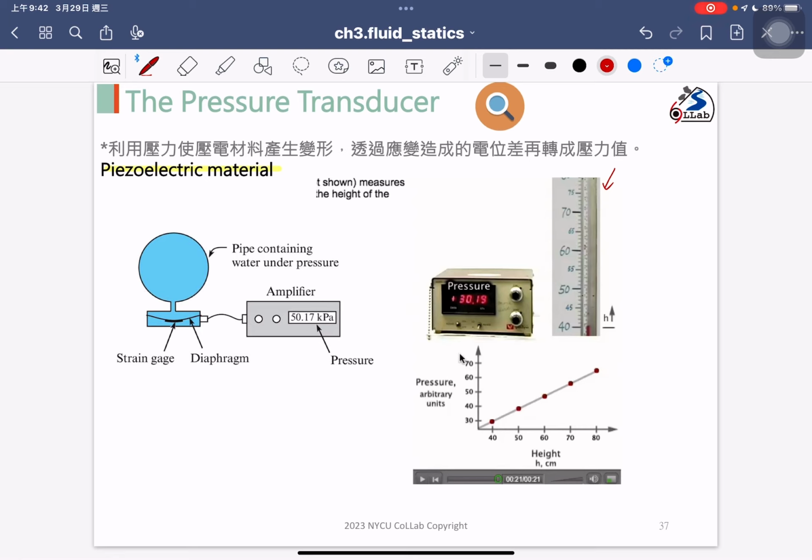With the traditional method, we can measure pressure based on the liquid height difference, so we can know how large the pressure is. And we will do some relationship analysis, a regression line, between the pressure units and the voltage changes, with a linear relationship to the height.